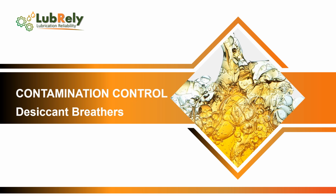Contamination prevention and control. When components change, or work is performed on the machine, make sure that all new components are free from contamination, and that further contamination does not enter the machine during servicing. In this video we discuss desiccant breathers. Desiccant breathers remove contaminants, such as dirt and moisture, from air entering machinery, sumps and reservoirs.